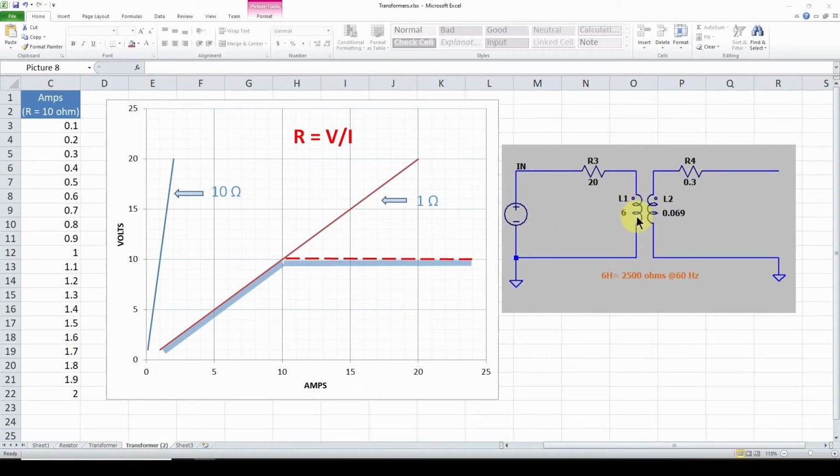So now the challenge is to figure out what is the characteristic of this. At what point does suddenly a little bit more voltage mean a whole lot more current? Ultimately, if you apply enough voltage here, this will be pretty much 0 ohms, and the only limitation to current flow will be this 20 ohm resistance of the winding that we calculated.